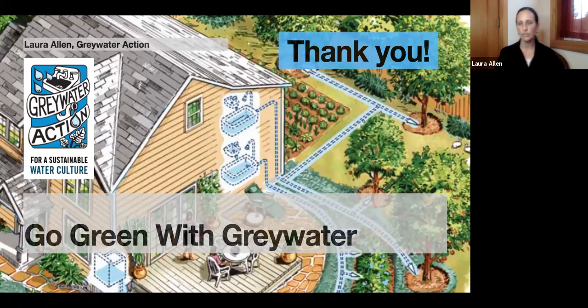You use your evapotranspiration rates for your climate. There are some online tools, there's a calculation, there are ways to do it. It's not too complicated, but there is one equation. If you're in California, there's an online app that's just great. It's called puddlestompers.com and there's an app called How Much Water, and you just pick your city from the drop down, say whether it's a high water or low water use plant, and how big it is, and it gives you a number.